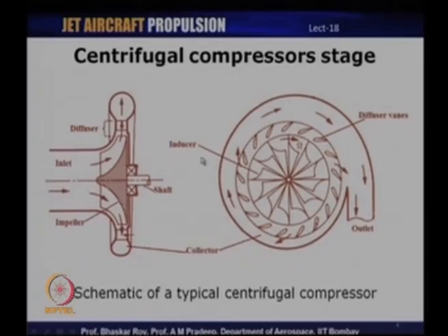And there is another component which is shown here, which is known as the inducer. We will discuss about inducer also in detail a little later. Inducer is one component or one part of an impeller. Basically, it is meant to drive or divert the flow smoothly into the impeller. In the absence of an inducer, the flow might enter the impeller with an abrupt change of direction, leading to noise and efficiency loss. So, that is the purpose of an inducer.